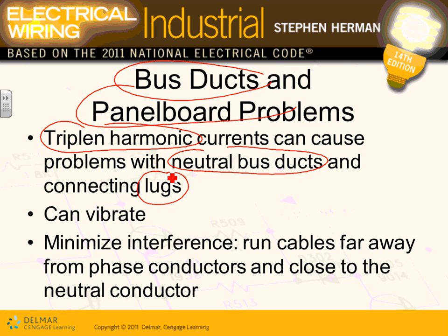A second thing, guys, is they can vibrate. Look at that. You walk into a bus duct and it's humming. The bus duct is humming and vibrating. That's an indication that you might have a harmonic problem. Cool.